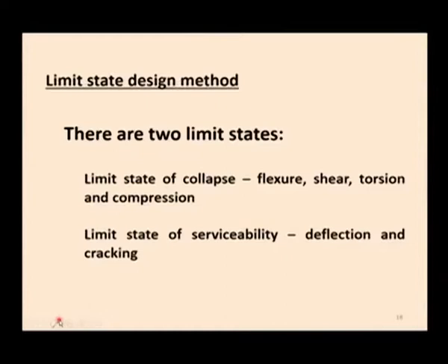The advantages of the limit state method over the other methods are these. Though the structure is designed to its ultimate loading conditions, they have added partial safety factors, 1.5 for concrete and 1.15 for steel, so the probability of failure of the structure in the limit state method is reduced to 0. In addition, in the working stress method and the ultimate load design method, deflection and cracking effects were not considered, but in the limit state method they are. These are certain advantages over the two previous methods.